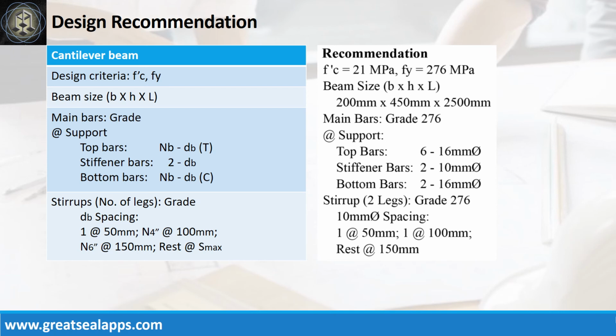Design recommendation as follows: f'c equals 21 MPa, fy equals 276 MPa, beam size is 200 mm by 450 mm by 2500 mm. Main bars of grade 276.